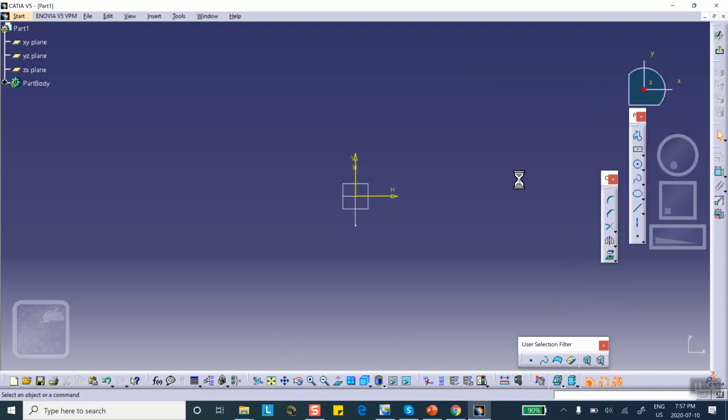Now, if you look at the previous video segment where I created the same model, I created 4 points, and then made the spline go through those 4 points. Those 4 points that I created individually, I had to turn into construction elements, because otherwise Catia will complain. It says that you cannot rib along that spline because the sketch is open. Now, what I'm going to do here is not create those points directly, but as I do this spline, I will input the appropriate coordinates.